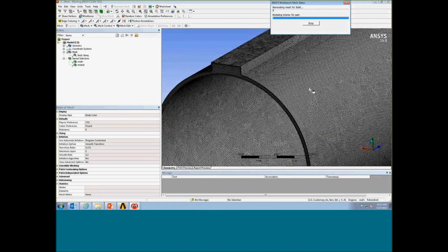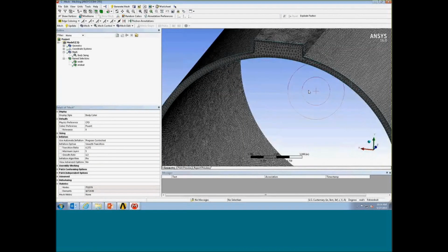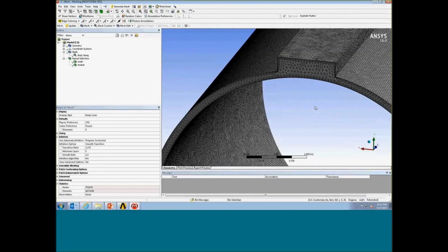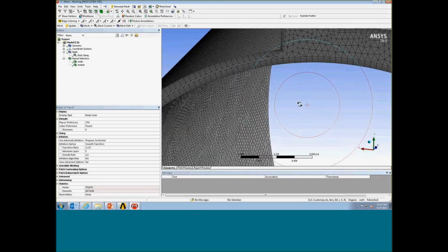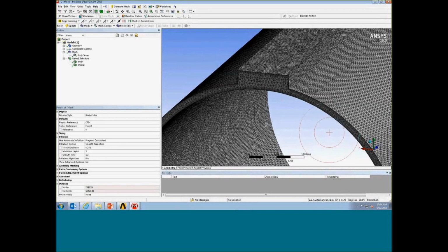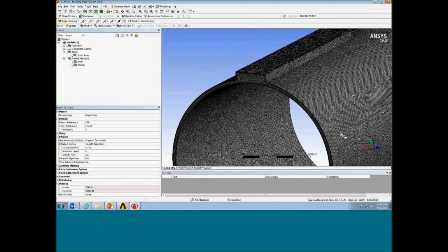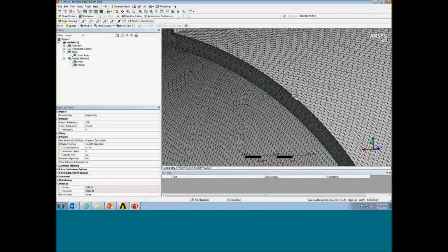So in this setting, now you see the meshing is complete, right? I mean, it did a great job. I end up having 5 prism layers inserted next to the boundary, just like what I specified for the default inflation layers, controlled by the program. And by using this mesh element size, I could resolve the gap quite nicely.